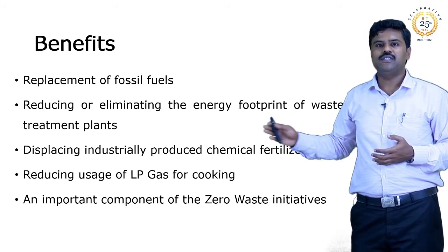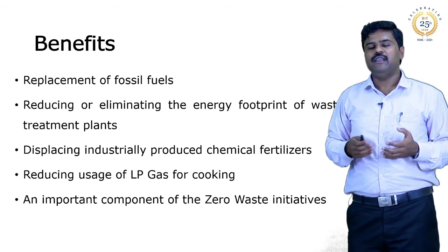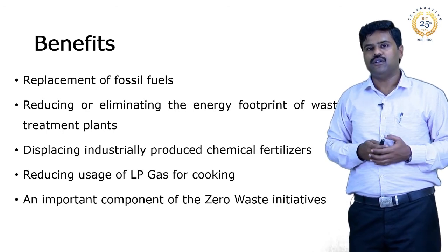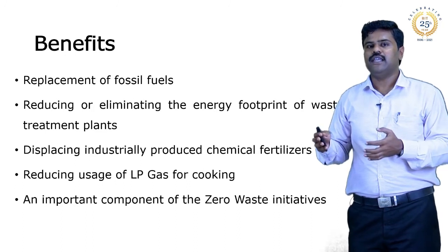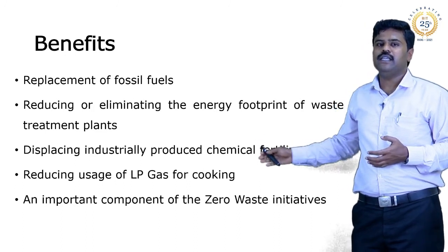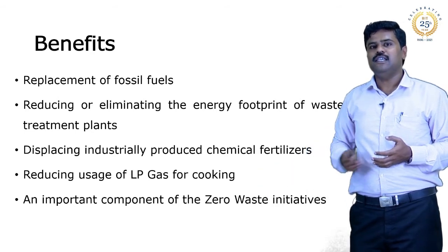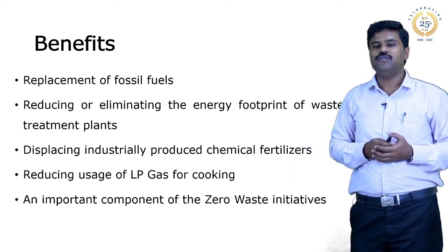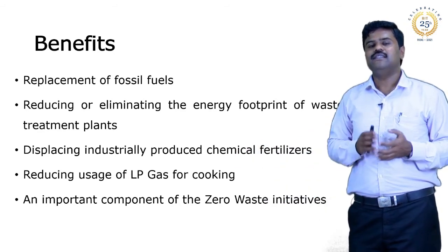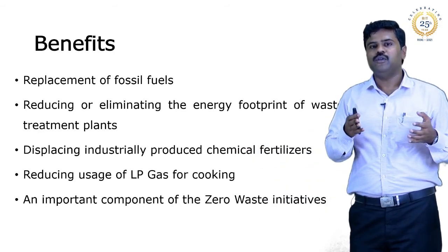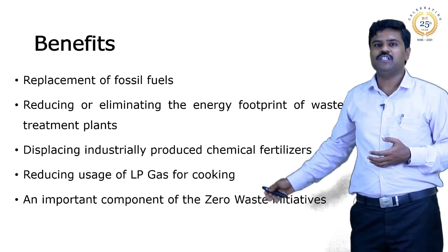Second is it reduces the energy requirement for the wastewater treatment plants, because for operating a wastewater treatment plant it requires a lot of energy. So if biogas is produced in addition, it can meet this energy demand. Then third is it replaces the chemical fertilizer. Then fourth is it replaces the LPG cylinders that we are using from the fossil fuels. Then finally, as I indicated, it is a zero waste technology. So whatever you are putting in, everything will come out as a product. So we can call it a zero waste initiative.